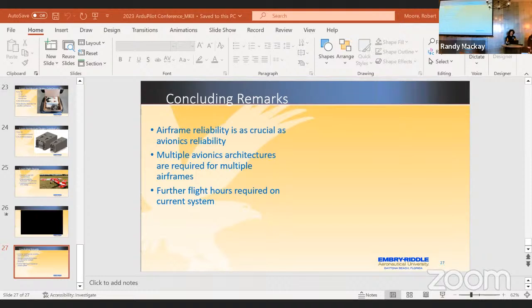Fortunately, it flipped to backup, landed with no issue. Carefully removed the primary, tightened things back up, did some vibration mitigation measures and went on my way. So more of an airframe-induced hardware issue, but not the hardware failing itself. That was a user installation error, not a physical hardware failure.